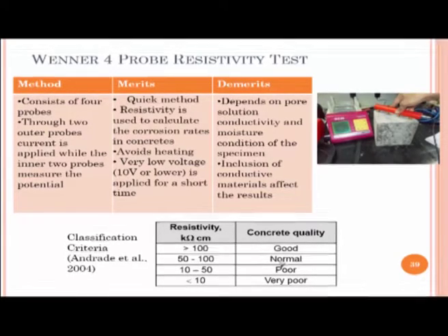So if you are testing resistivity of concrete, you have to maintain the same condition throughout the test. It should always be moist or it should always be dry. For conservativeness, we always want it to be moist because that is when we get a lower value of resistivity. And please remember, as I said earlier, more resistive the concrete, the less permeable the concrete. In other words, higher resistivity means a better resistance to penetration of liquids and better resistance to corrosion. Higher resistivity, better resistance to corrosion.